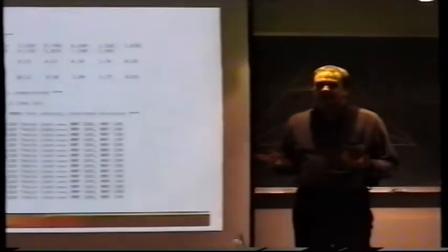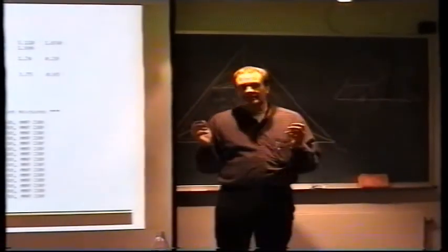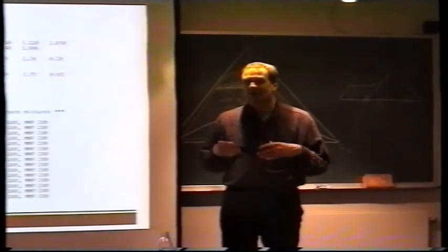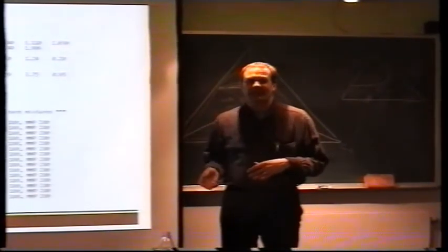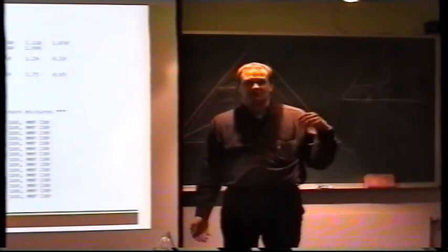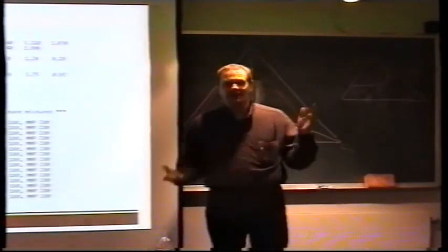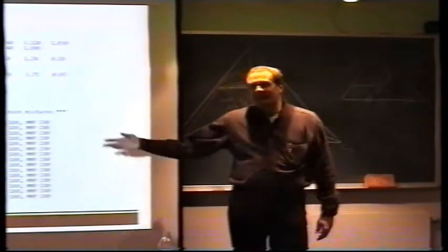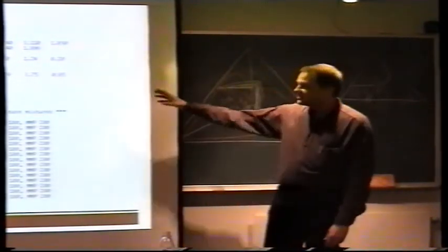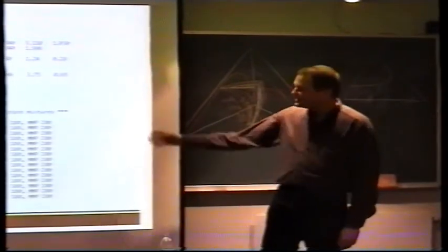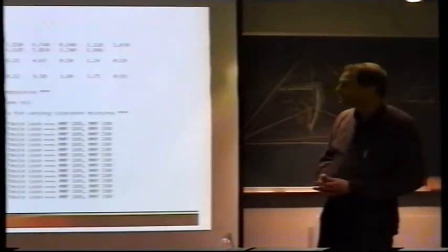If you wanted to do the slim tube simulations, you would have to make roughly on the order of 20 or 25 individual slim tube simulations. So you're talking about 20 or 25 data sets. Each one, the data set that is required by a reservoir simulator, and you know how complicated those can be. It'd be a nightmare to put that together. And this is just one simple 2-page data set, and you get the whole suite of results.